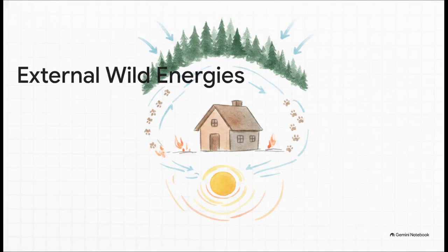We're looking at summer and winter sun arcs, prevailing cold winter winds, hot summer winds, water flow, and flood-prone areas, wildfire vectors, and even wildlife migration corridors. The whole point is that by synthesizing these incoming vectors onto your map, you can actually consciously design your landscape to deal with them. You could erect shields, like a dense tree line to block a freezing north wind, or you could open up a clear sector to let that low winter sun passively heat your home.